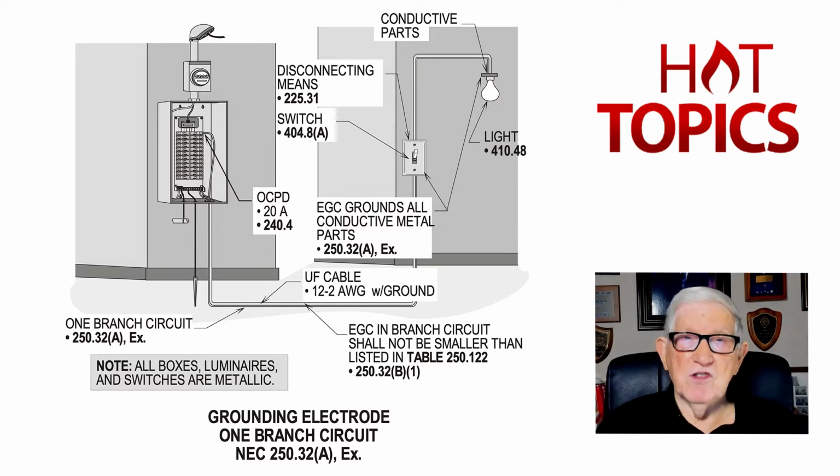And that would be considered a multi-wire circuit. But if you run a hot neutral, hot neutral, hot neutral, in other words, 3 individual ungrounded conductors, 3 individual neutral conductors, you're not a branch circuit anymore. You would have to set a panel board, see. So that's the exception that we could use there.